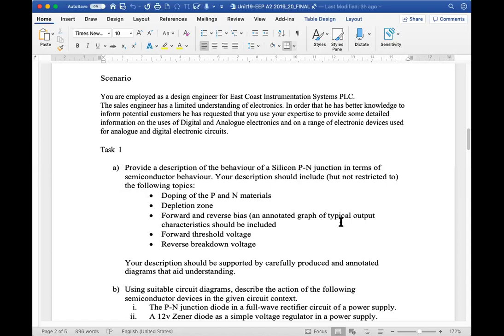Task 2, this is like learn and outcome 4. So part A is a pass, pressure sensor, instrument range has an output in the range 0 to 10 volts. Pressure range is 0 to 10 bar. Suitably annotated diagrams to explain the differences in the way analog and digital systems would represent the voltage output.